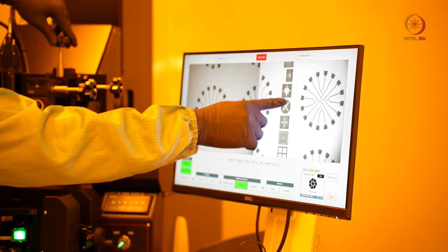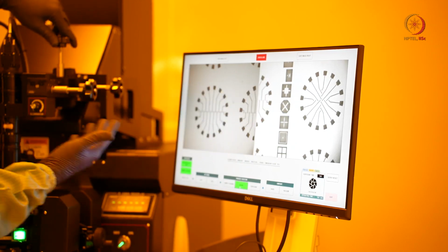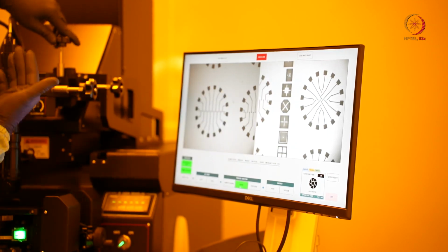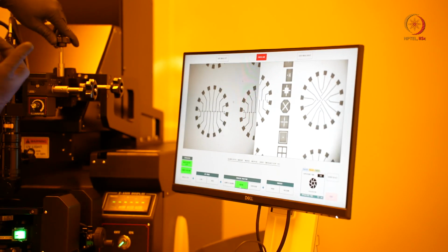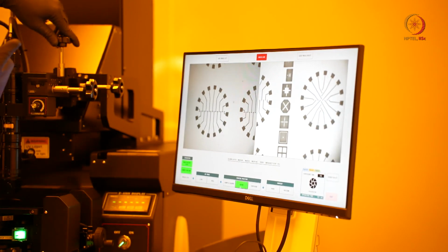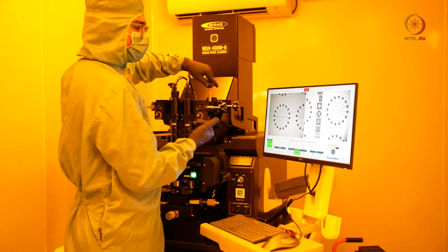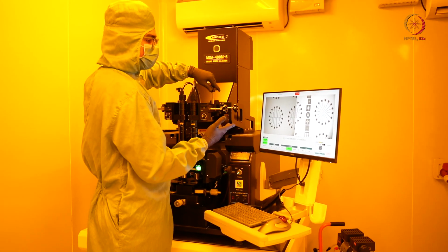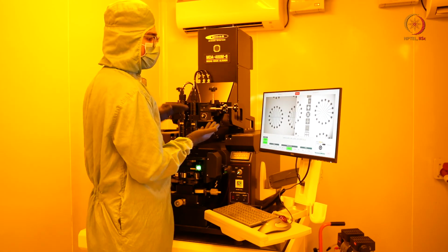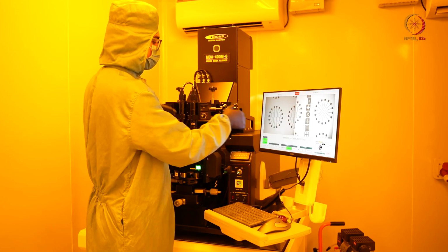And these designs that you see here are known as the alignment marks. So if we have a multi-step process or multiple deposition, lithography and etching steps, or multiple lithography, lift off and other steps, we will need to align one process step with the other. So for that we use the alignment marks.